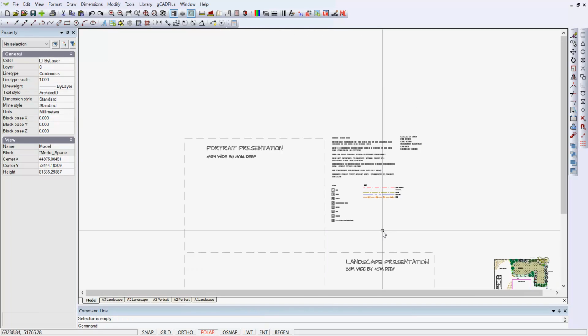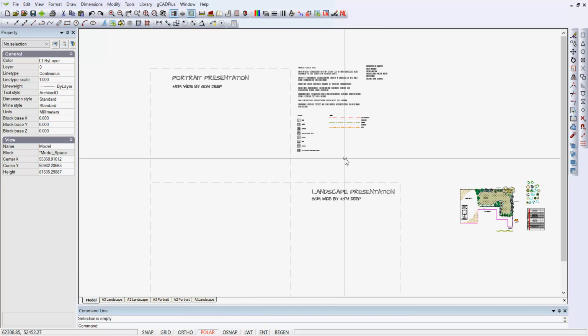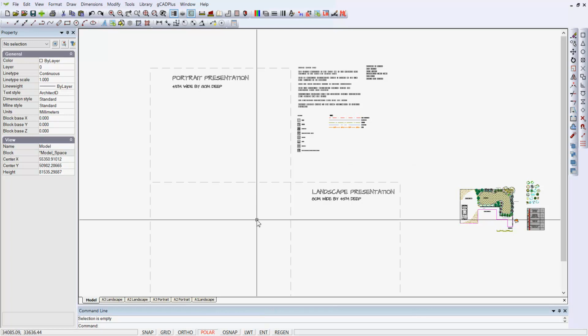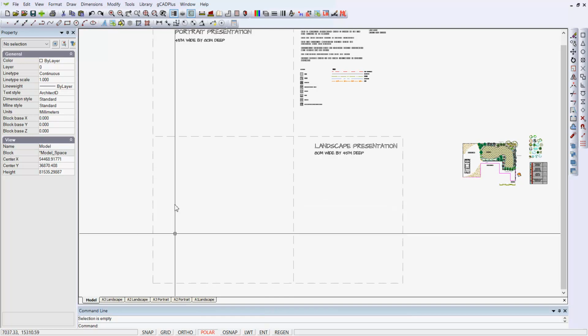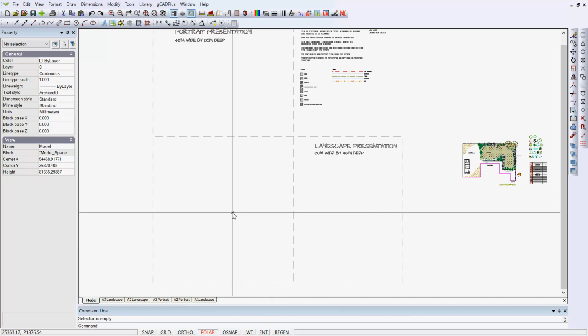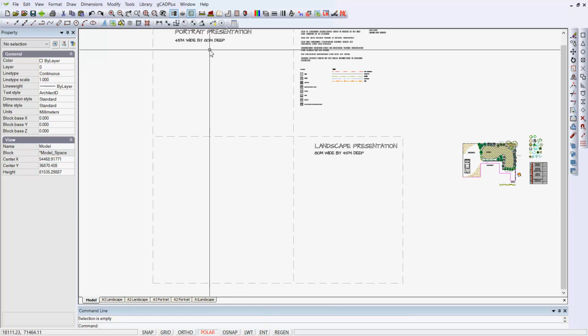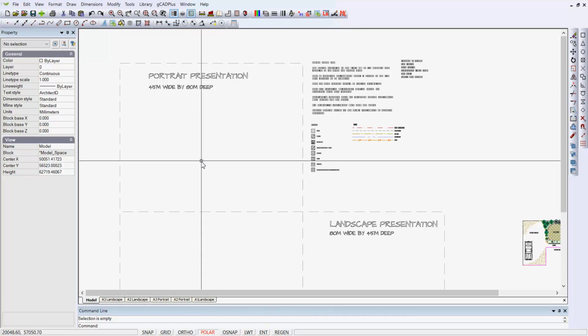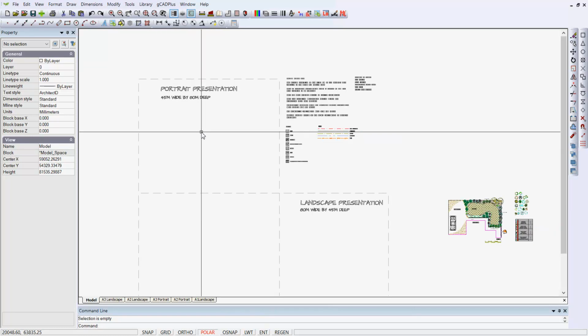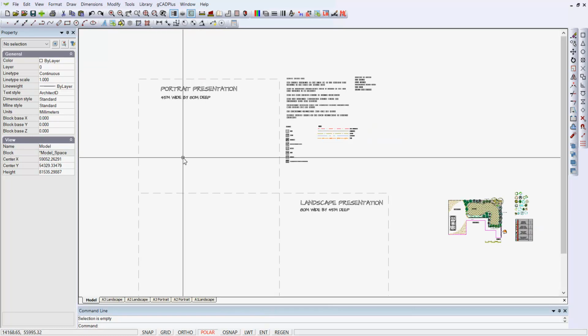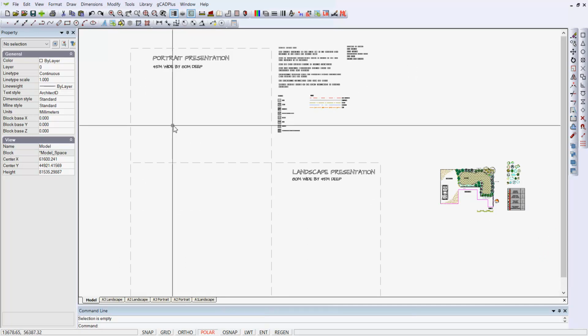So the key piece of information here when you start, or when you're talking to your design team, is if the site would fit, or you would prefer it to be in a landscape presentation, you develop the site in this area here on the bottom left, and if it might be a long narrow site, this dotted line here represents a long site that's roughly 45 meters by 80 meters deep. These sizes are not fixed, but you can play with any size you want.